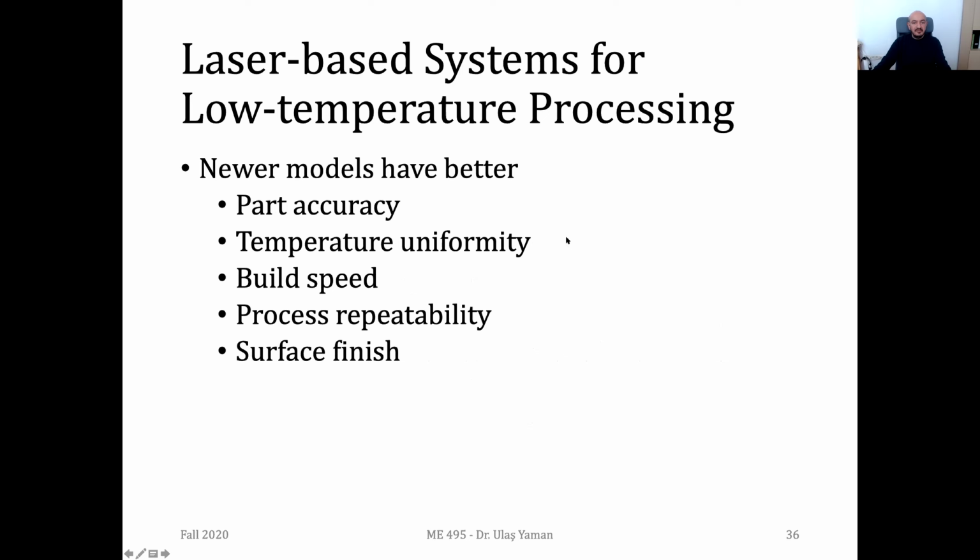Okay, and now we have, with the help of these improvements in different technologies like laser, optics, handling systems, and powders, since there are companies working on the sphericity of the powders and they want to obtain pure spheres all the time. These days, the new models have better accuracies and better temperature uniformity, since sometimes they put thermal cameras inside the machine and check if the temperature is uniform.